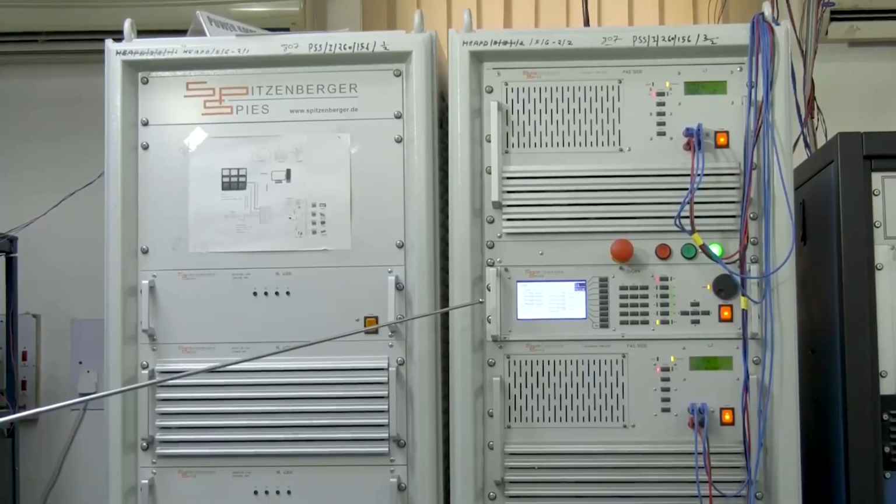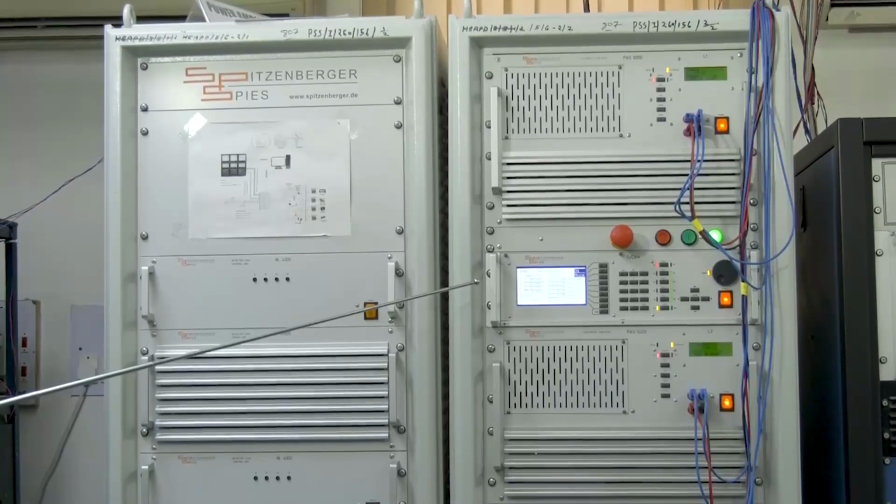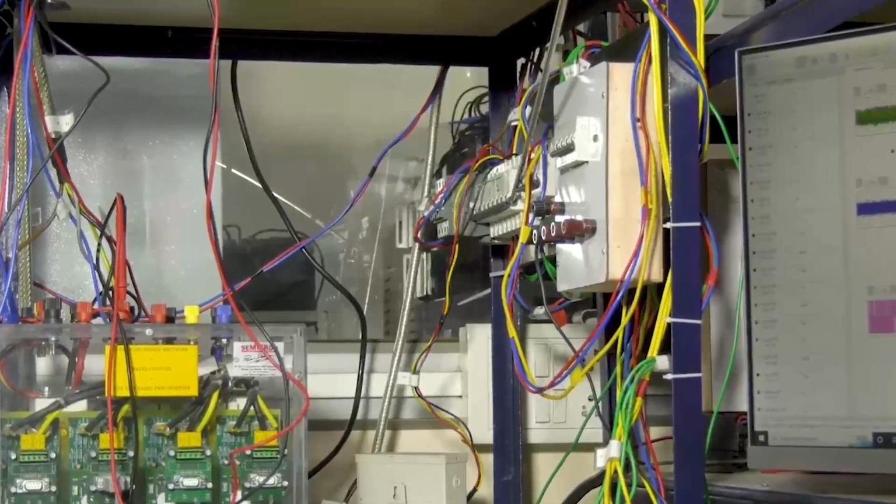While the stator of the slip ring induction motor is connected to the power amplifier via a switch, the switch is initially open and is further closed when the stator voltage and phase angle are synchronized with the voltage and phase angle of the grid using the rotor side converter. After synchronization, RSC regulates DFIG to operate in the speed power control mode. Rotor of the slip ring induction motor is connected to the RSC, which is controlled in the FPGA platform.